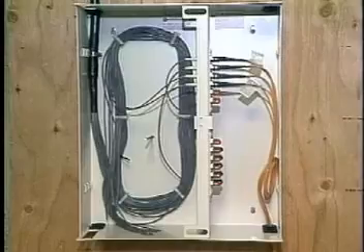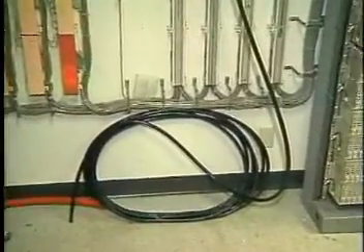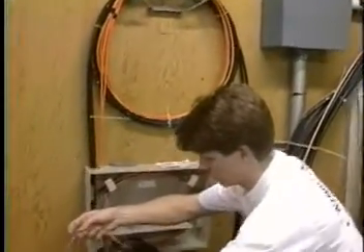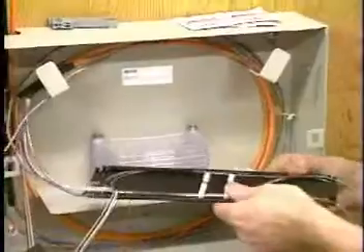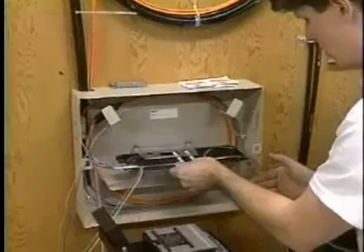Because the exact location of the cross-connect may not be known during cable installation, always leave more cable than you think necessary. The cable is dressed and mounted along with an appropriate amount of slack, with any excess cable pulled down to the floor below, where the process is repeated. By leaving adequate slack during cable installation, you can eliminate unpleasant surprises later in system construction.